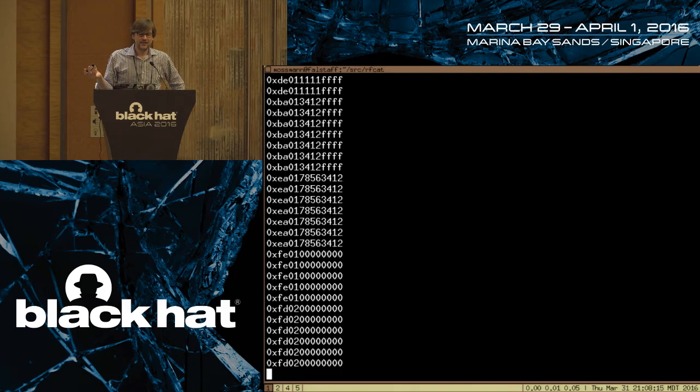And when I changed the action code by just a little bit, the checksum changed by just a little bit, which is a good indication that this is a simple checksum algorithm. It's not a more complicated algorithm like a CRC, but only an 8-bit checksum, and it looks like just a simple addition or subtraction of all of these things.